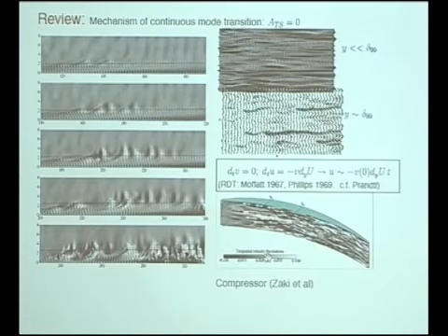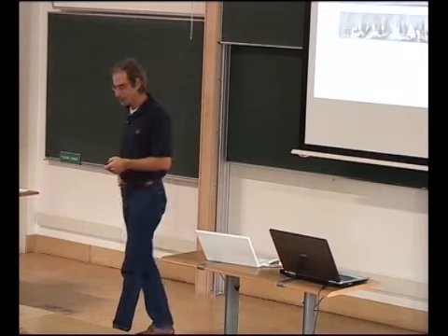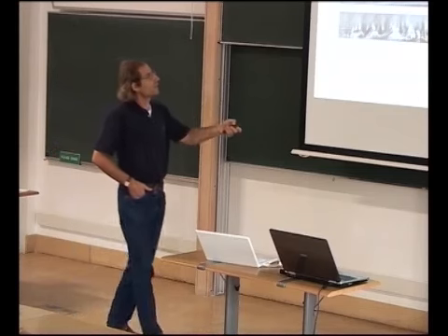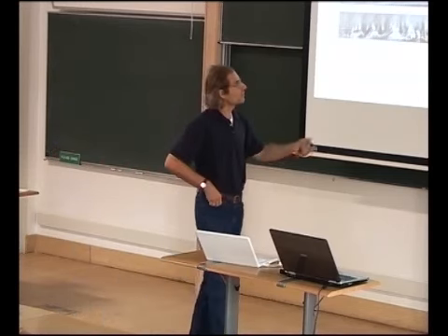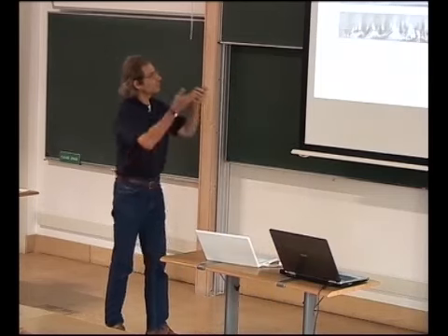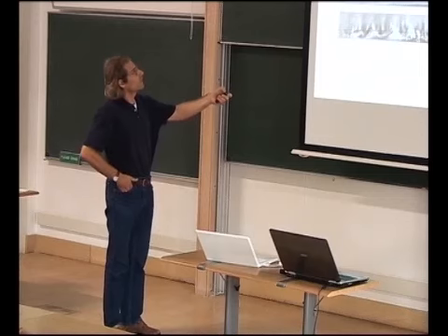The downward displacements cause high-speed regions, which in terms of velocity vectors look like jets in the positive direction. The upward motion produces negative velocity fluctuations, which look like negative jets. And that's near the wall. If you go to the upper part of the boundary layer, you just see the upward moving disturbances, which are long negative jets. And those turn out to be the origin of transition, at least in our computer simulations.